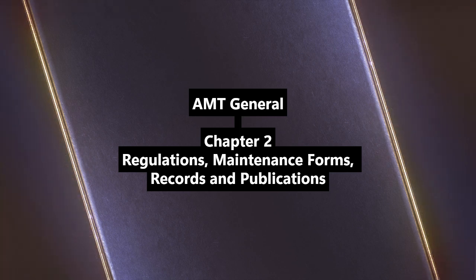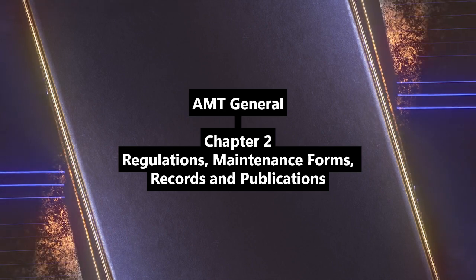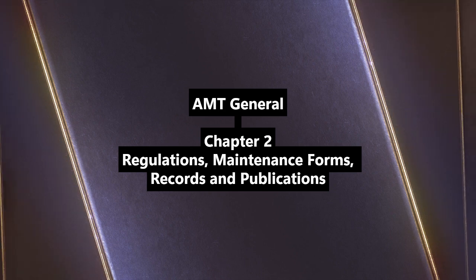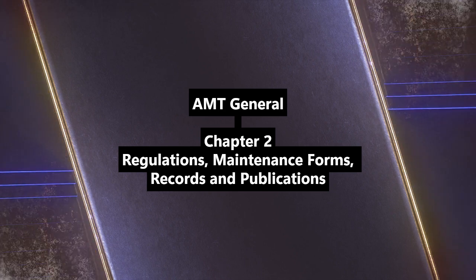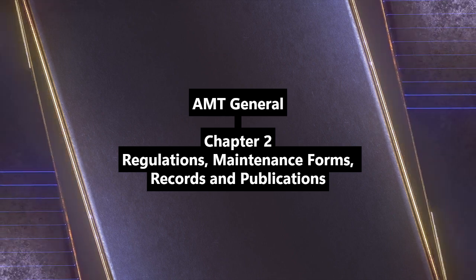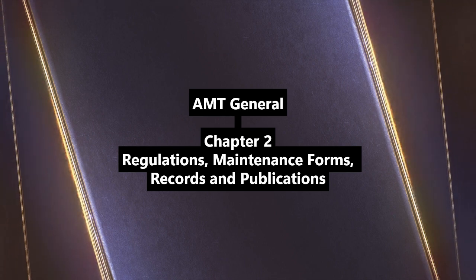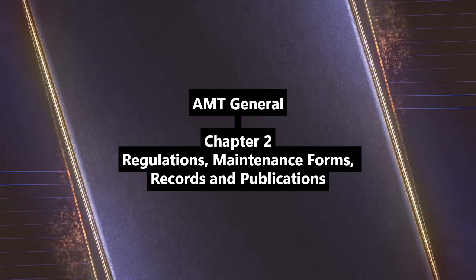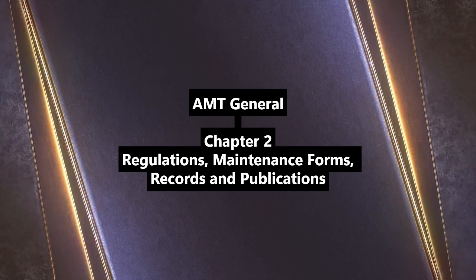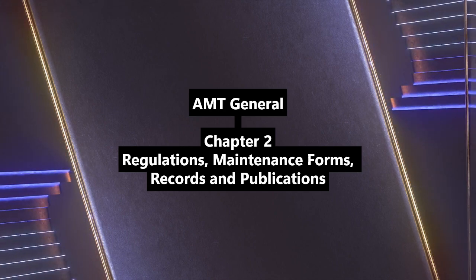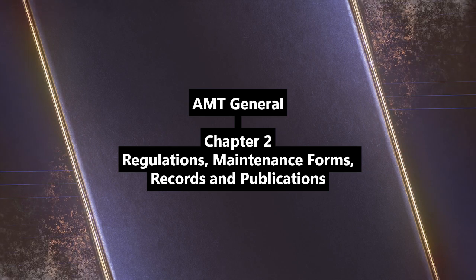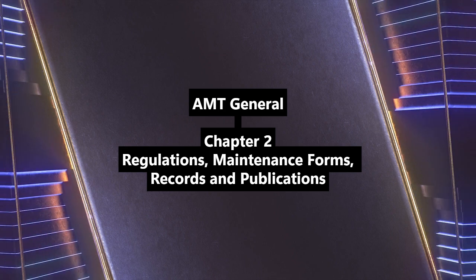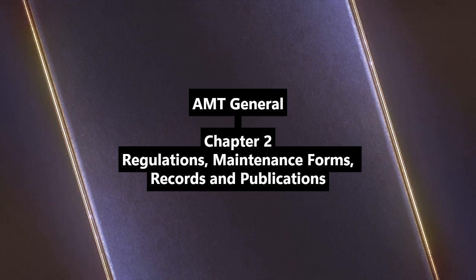What about Part 121? 14 CFR Part 121 covers the big airlines' operating requirements: domestic, flag, and supplemental operations, scheduled or unscheduled transport for hire. Domestic, flag, supplemental. What defines those? Schedule, where they fly, and aircraft type. Part 121 generally applies to turbojets, planes with 10-plus seats, or over 7,500-pound payload for domestic and flag. Supplemental ops usually involve even larger aircraft. And they need specific management roles. Yes, Director of Safety, Director of Operations, Director of Maintenance, Chief Pilot, Chief Inspector, a whole required structure.